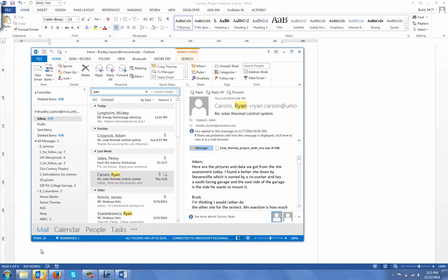How do you control your solar thermal system? Which one? I've got two of them in my house. Do you have an air-to-air one? Yeah, both of them are. Okay. What kind of controller do you use? One is just manual to turn on and off. The other one has a thermostat in the exhaust side, and when it reaches 120 degrees, it turns on the fan.